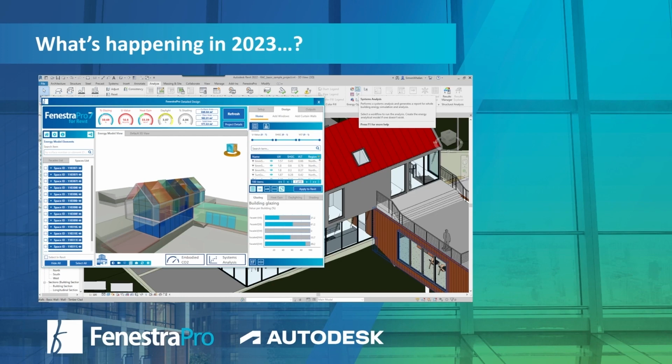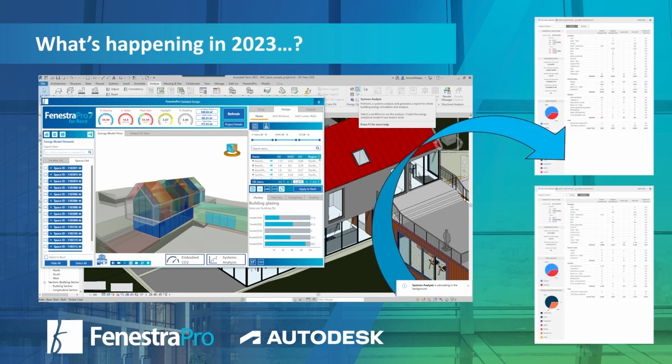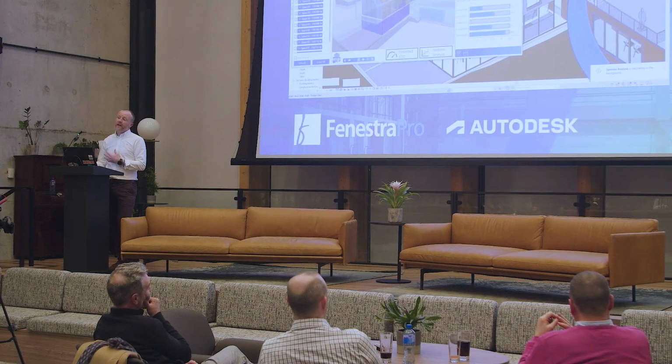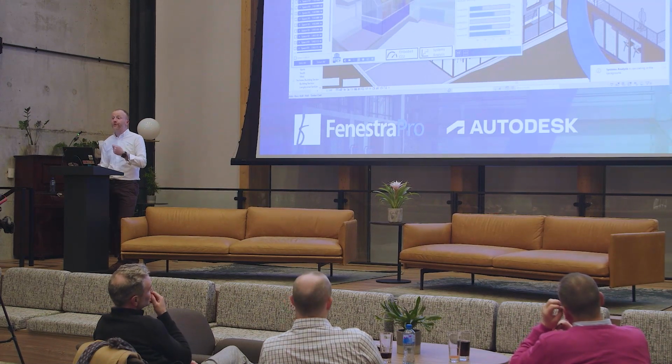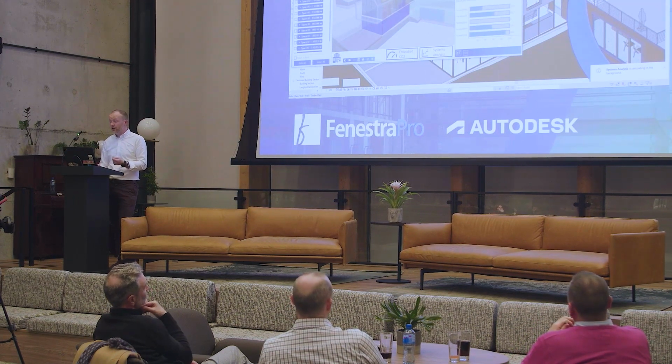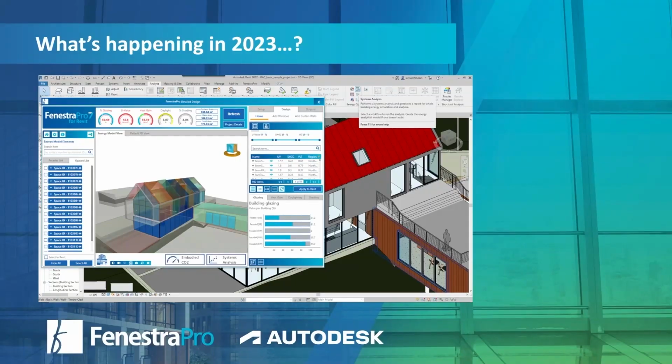So we're starting to put in this idea of embodied carbon and systems analysis, using the systems analysis piece in Revit. We can execute that systems analysis event and then pull that information. That's created from Energy Plus, I think, if I remember correctly, all of that whole building energy use. We can then extrapolate or scrape that information to just the stuff that your envelope relates to or your envelope is driving. So we can show the energy use and therefore the emissions relating to your envelope. And then likewise, the embodied carbon.